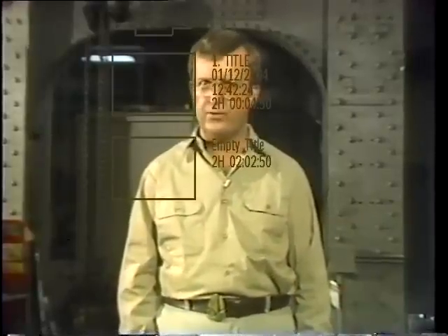We've now covered 4 groups of lubricant materials: animal, vegetable, mineral, and synthetic, and 4 properties of lubricants: viscosity and the viscosity index, flash point, fire point, and pour point. We also went over 4 factors that affect lubricant selection: pressure, speed, temperature, and environment. So why don't you take some time now to read through all of the material we've discussed so far.